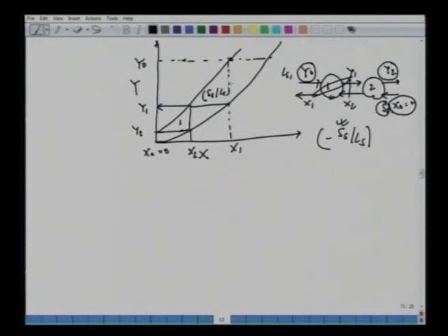So look at this, if we don't have a correct estimate for the slope here or the amount of solvent Ss, then we get some values which are smaller than this. That means one will have to adjust the values of slope to obtain exactly y0. Alright, so going back to this slope, one will have to adjust the slope here. So it requires some iterations to obtain this two stage process, where we have brought down the concentration of feed from y0 to y2, and the solid phase concentration has increased from x0 to x1 by two stages, stage 1 here and we have stage 2 here.